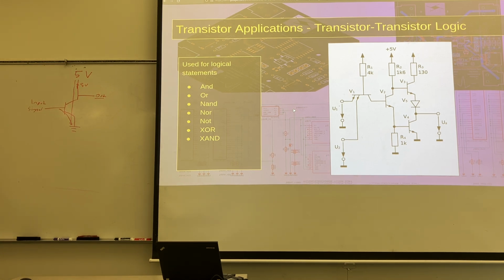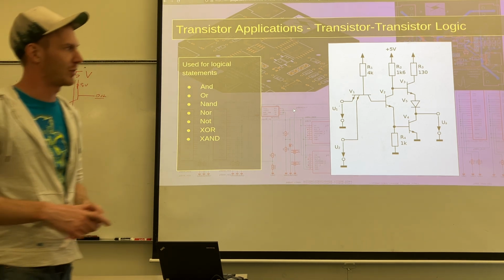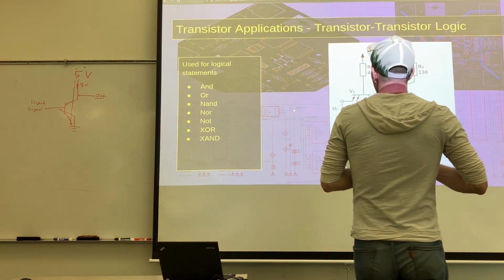The converse of that is if your input is nothing, this is not shorted to ground, this drops no voltage, and this is now 5 volts out. This is all again relying on infinite impedance outputs, so you hook this up to another MOSFET and that would do the actual work, because otherwise you send actual power that way and you don't want to do that. But that's the most simple concept of what we're doing with this.